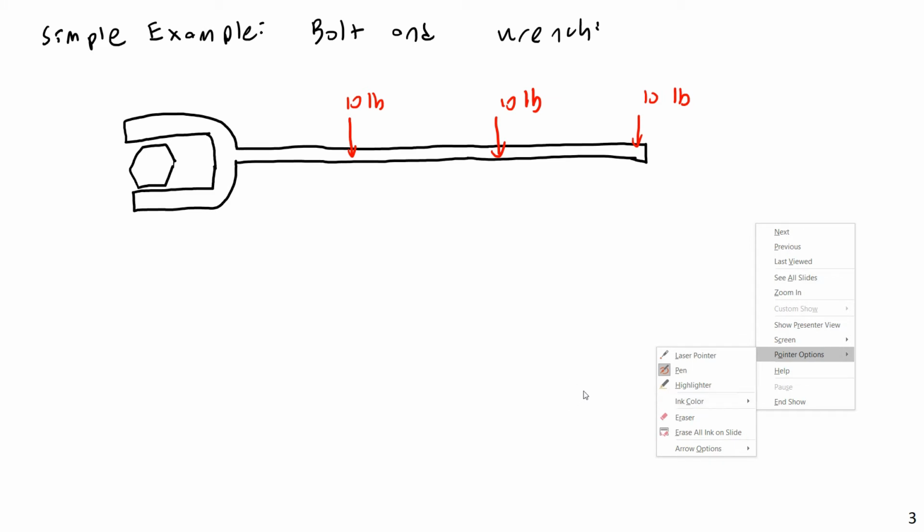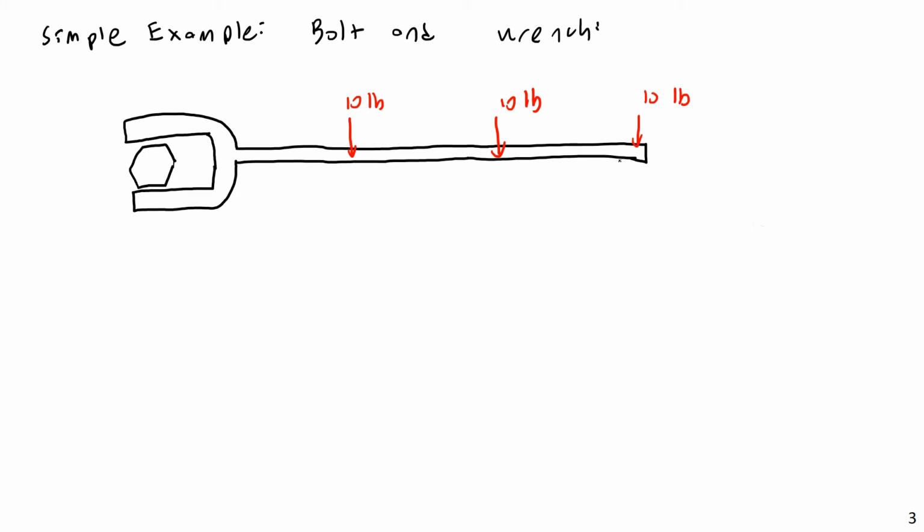And in fact, if you find yourself unable to turn a nut, you can use what's called a cheater pipe, where you put a big long pipe on the end of the wrench. If you're not able to generate enough force, you can give yourself a little bit of extra moment arm and open it that way. Of course, you do have to be careful. Cheater pipes can be good in small doses, but you might think, oh, if a 1-foot cheater pipe is good, a 15-foot long cheater pipe will be even better.